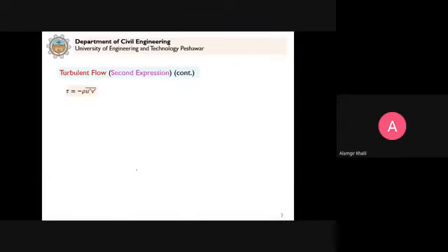Now if we proceed, this is the expression that we get, clear? And this is known as the Reynolds stress, because you get the stress units. Shear stress is given by this quantity, clear? But then the problem is that we have to measure this product of fluctuations for a long period of time. So it is very difficult to measure this quantity.